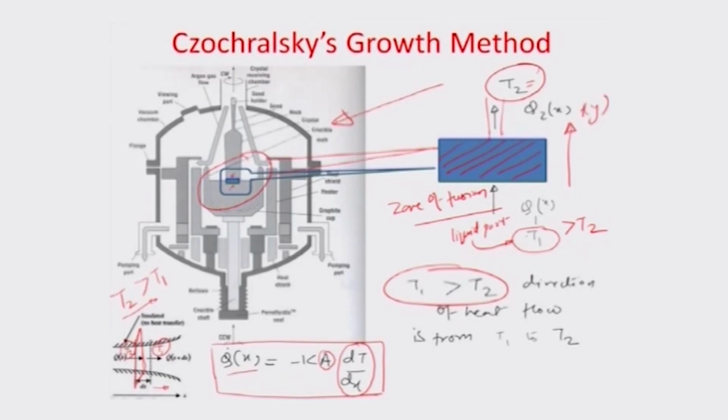Okay, so, the heat flows from T1 towards T2, and we need to just investigate how the rate of heat flow into the zone of fusion from the liquid side and the rate of flow out of the zone of fusion to the solid side would be balanced with each other, and this heat loss which is happening is also a cause of the formation of the solid, which means that in a solid state, as you know, the bond energy is always higher, and therefore, there is a heat of formation of the solid which is lost.